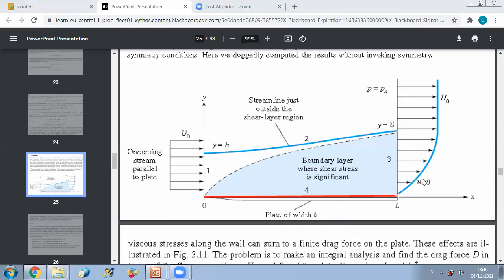Okay, so this is our control volume. If we neglect the weight, and even if you don't, the weight is in which direction? In the vertical, and you will have the normal force opposing it. So we don't care about forces in y, since motion is along x, so we will write our linear momentum relation along x. Okay, so along x, what do we have? We have the drag force exerted by the wall on the fluid. Now we have atmospheric pressure outside.